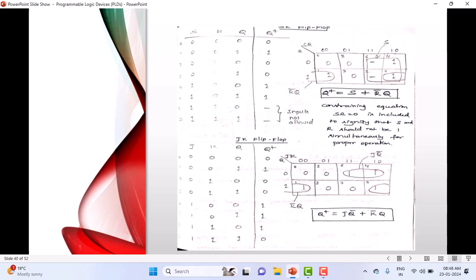How do you represent the K-map? 0, 0, 0, 1, 1, 1, 1, 0. You must write this, since the two variables are there above the diagonal. I have written all possible combinations such that only one variable changes. From 0, 0 to 0, 1, you can see column-wise on the K-map, there is one variable change. I can't write 1, 0 here, because there would be two variable changes. So I have written 1, 1 here.